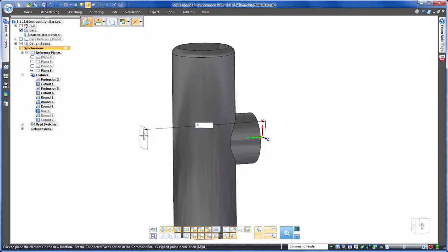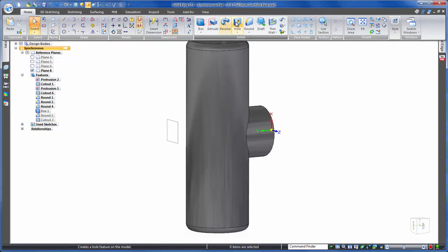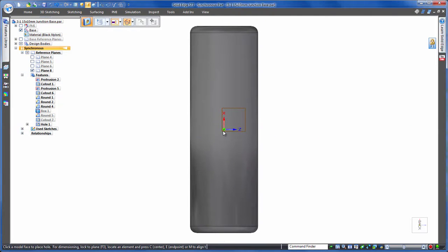In this example, we're going to create a custom fuel adapter starting with a basic body and then simply reuse design details from other Solid Edge projects to complete. First, so that we know where our output ports are going to go, we'll quickly create a few holes. And notice how quick we can space these, no separate dimensioning tool required.